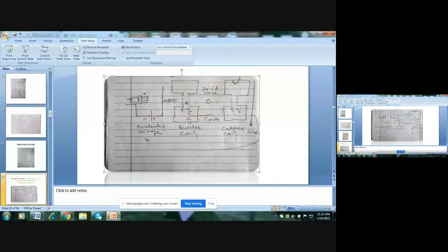Suppose we have to design a cavity for 10 to the power 9 hertz, which means 1 gigahertz. Then the dimension, or volume, is V1. If we have to design for 10 to the power 11 hertz, then we have to reduce the dimension. So frequency is inversely proportional to the volume of the cavity. The RF field is produced due to this electron bunch, and this is called the perturbation method of cavity excitation.